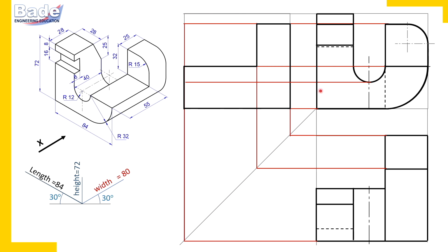This is the front side and this is the back side. So from the front, 40 millimeters parallel to width, you can measure independently. And I generally prefer measuring independently for smaller details. Otherwise you can take projectors. Since you have already measured 40 millimeters parallel to width here, you project it here. So this is how we got 40 millimeters parallel to width, and complete the dotted rectangle.